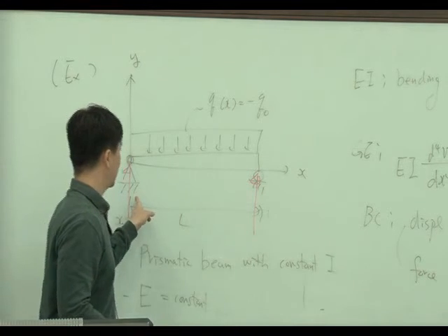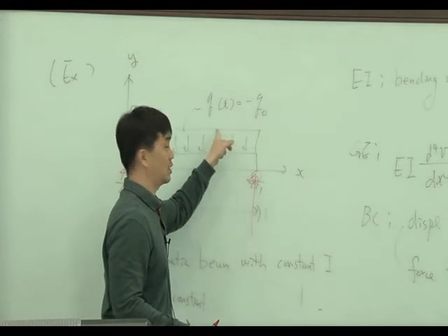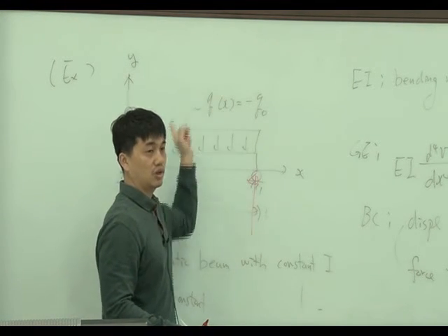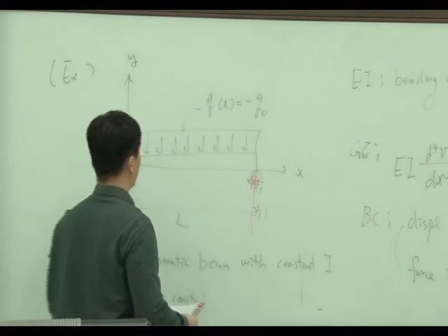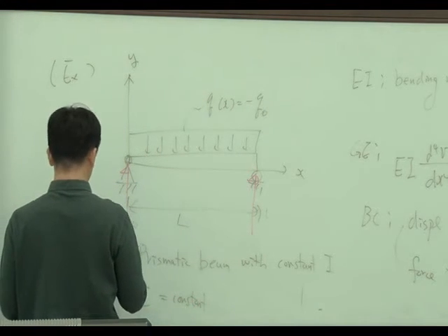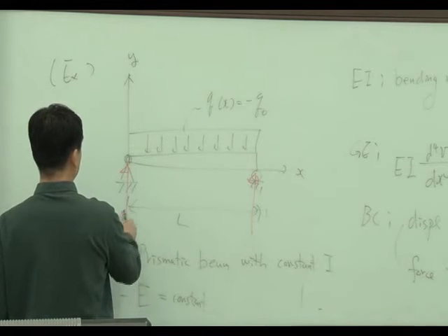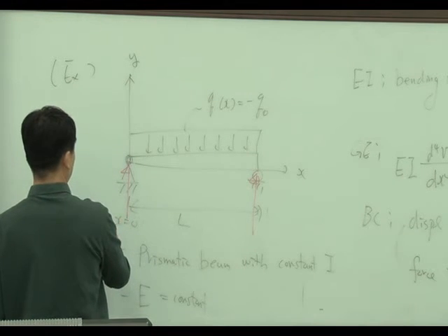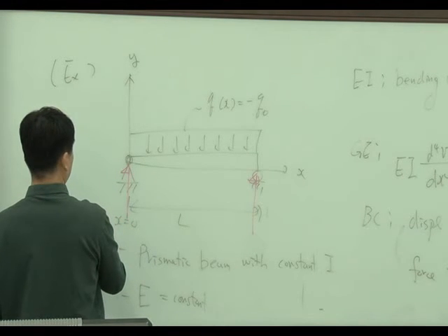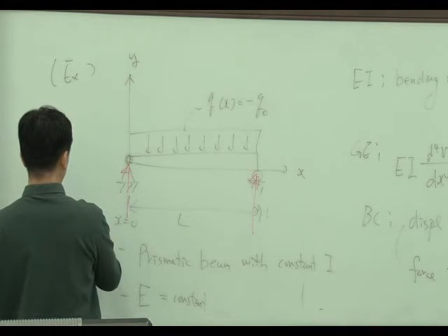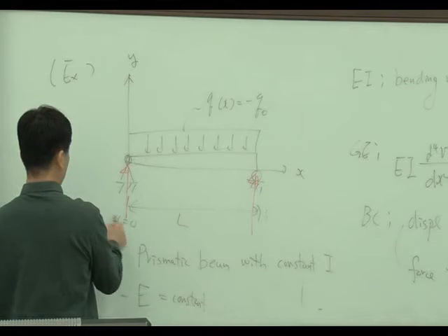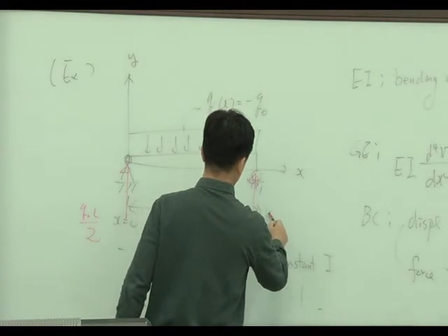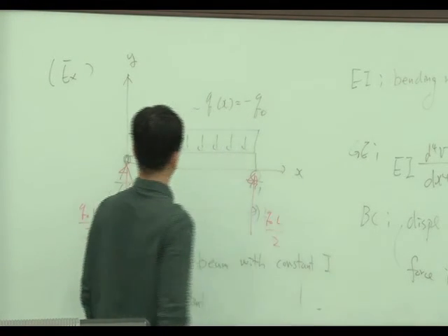Also, this reaction plus this reaction should be equal to the whole force in the y direction. So here the reaction will be q0L over 2, and here also q0L over 2.